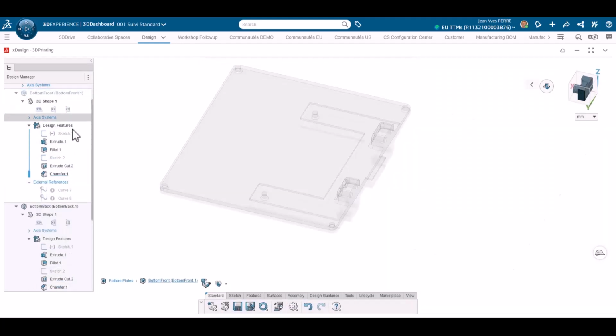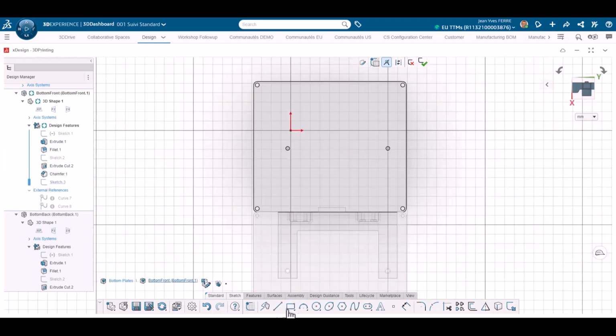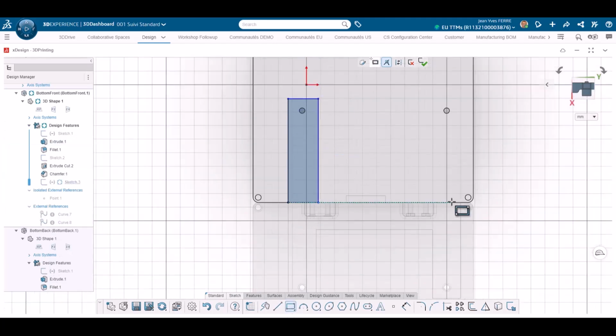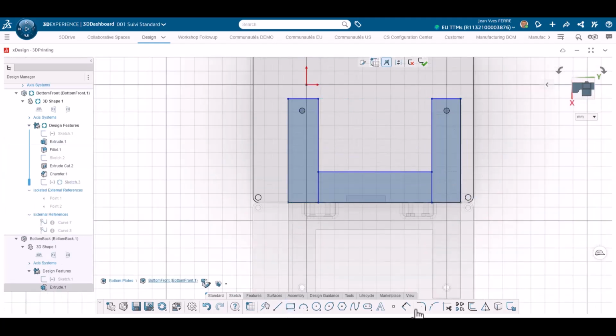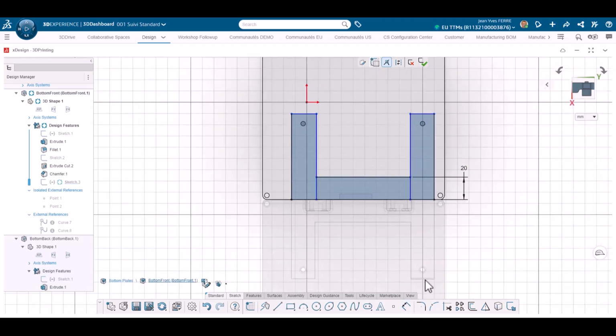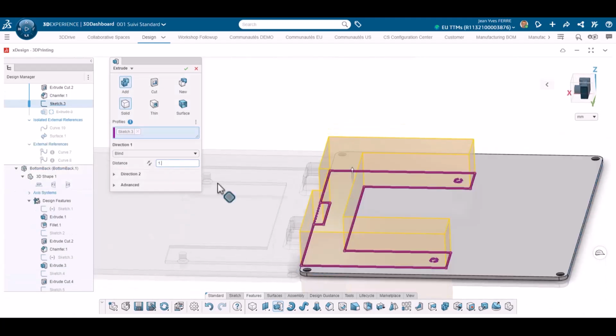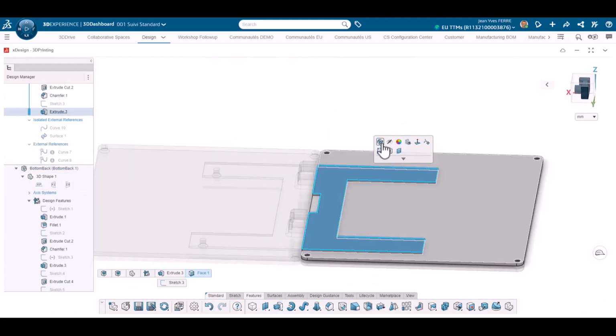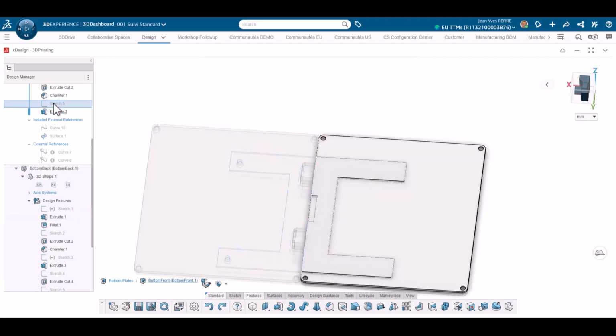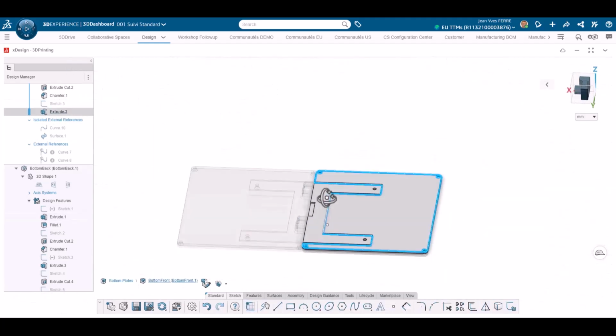Now I can take care of the other bottom plate. I create a sketch aligned with the opposite part and add mirror and equal relations to position them with the same dimensions. I also create a jog to host the opposite lip with an offset, and I add the same thickness as the other part. Stability is key for my hard drives. I also forgot hole contours in my sketch, easily corrected.